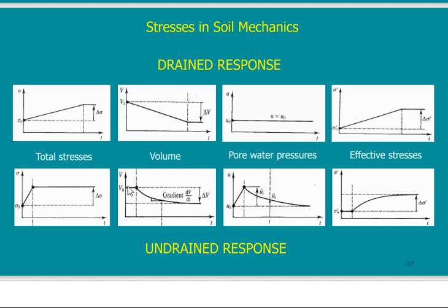You just put the load, it will not just go. No, you have to discuss something. Please leave. We have some load coming, and so something like this. So at the start, you have to wait for a while till water starts to seep outside. Once it starts to seep outside, then the volume will decrease gradually. So this curve is completely different than this one. So the case of drained is completely different than the case of the undrained.